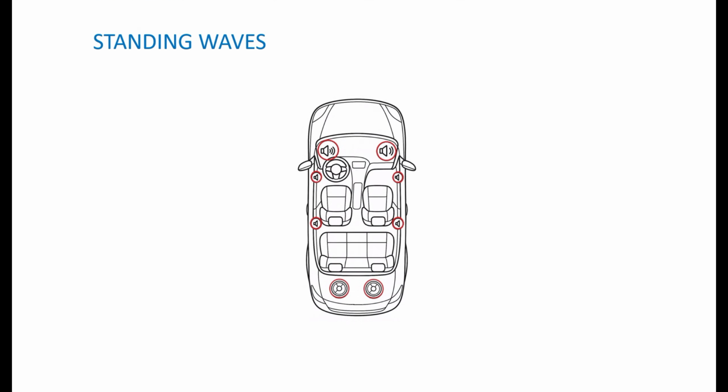All right, the next topic I want to talk about is standing waves and cabin gain. Now, these are acoustical phenomena that occur inside your cabin, and they're driven largely by the cabin dimensions. I'll talk about standing waves first and come back to cabin gain in a moment. But these two things are interrelated, and I'll explain why. But first, standing waves. A standing wave is a phenomenon that occurs when a sound wave bounces off a reflective surface and then interferes with itself, right?